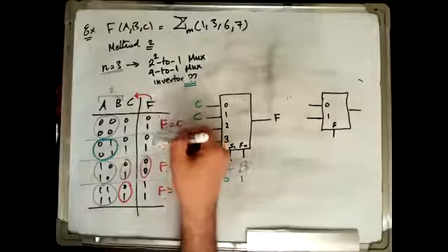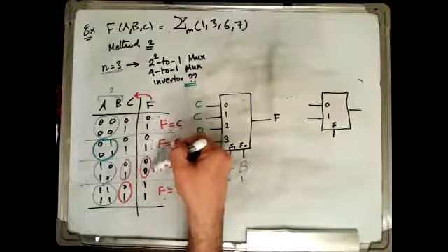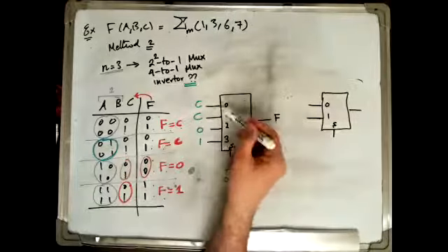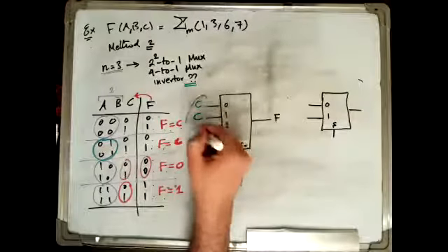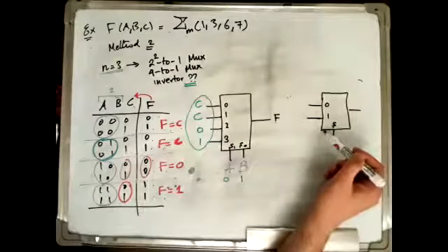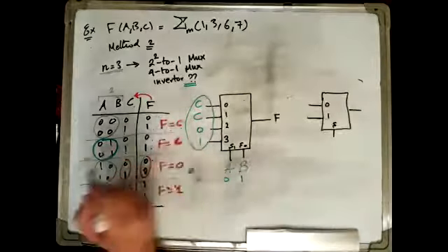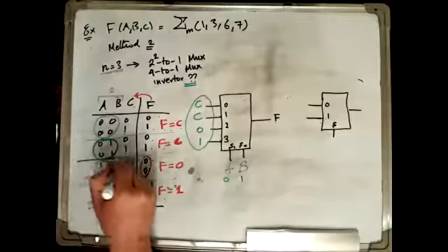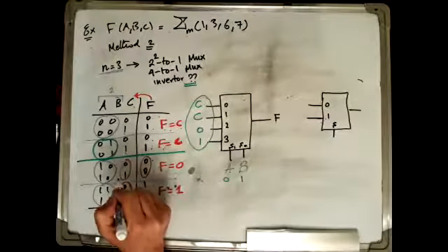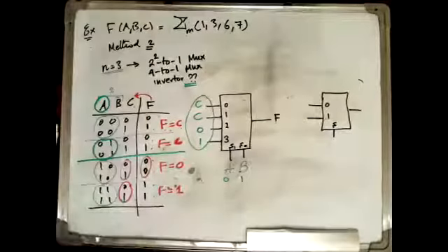Using the multiplexer to implement this function, I need an 8 to 1 multiplexer because I have 8 choices. But when I had only hardware that supports 4 choices, I needed to express the inputs in terms of the remaining variable. Now I reduced the size of selections in the hardware to 2 selections only while I have 8. What does this imply? I will need to split the table into 2 sections, and to do that, how many variables do I need? I will use only one variable, which is the most significant variable.